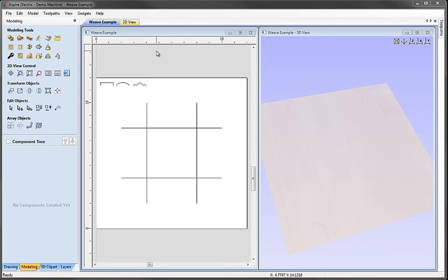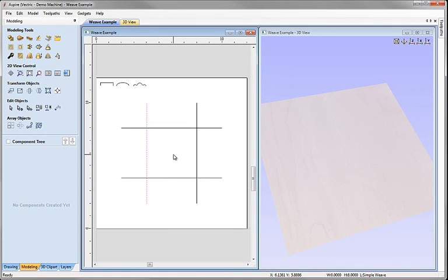Something else that could be important is the order that the shapes are weaved in, as in which parts go up and which parts go down. You can control this by reversing the first drive rail that you select. In order to do that, you need to make sure that you have actually selected a single drive rail like this first and then selected the others. The order doesn't matter that you select the others in at the moment. So we know that this is our first drive rail here.